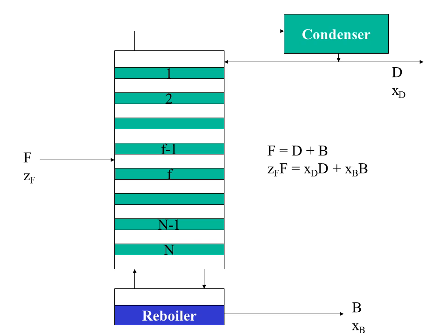We'll take advantage of, with a binary mixture, doing two material balances, one being a total balance where the feed F is equal to the distillate plus the bottoms, and then looking at our one component, the mole fraction of it in the feed times the feed flow will equal the distillate mole fraction times the distillate flow, plus the bottoms mole fraction times the bottoms flow.